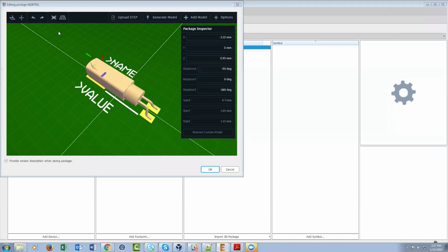But in 3D, you're not going to see anything because all the 3D functionalities of Eagle are cloud-based. So yes, you will be able to use the library as long as you've downloaded the managed library first. Okay. And let me see. This is from a custom library that is managed.